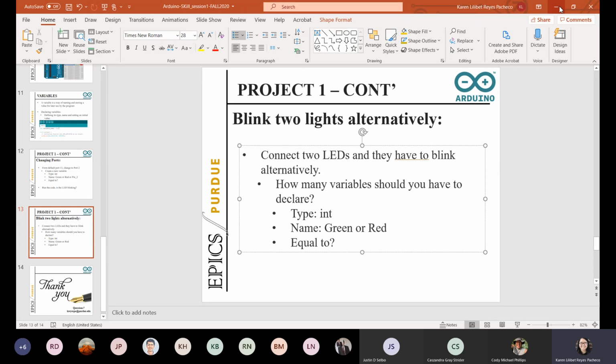Well, I see that you're missing several parts. So you are missing a resistor. I see that your green LED is missing a resistor as well, so copy exactly the same connection as the red one. And then you also need to modify your code. So you are just making it work for the red one. It's really good that you added the two variables. However, you still need to add more code in the while loop.